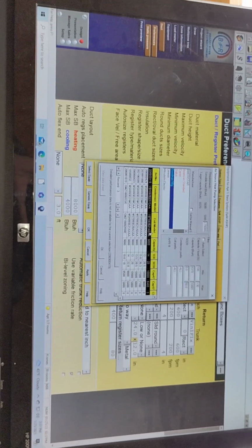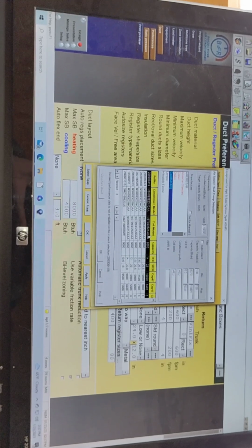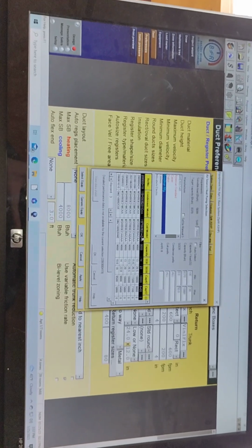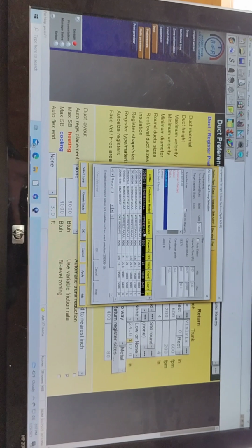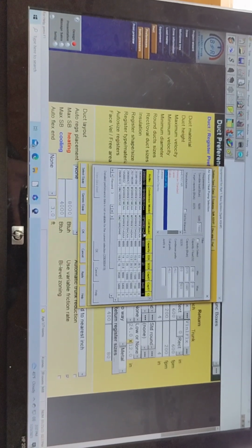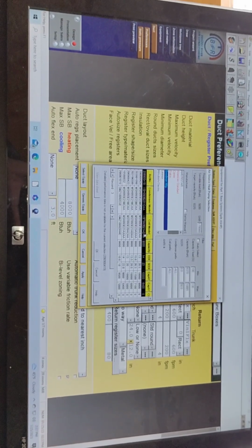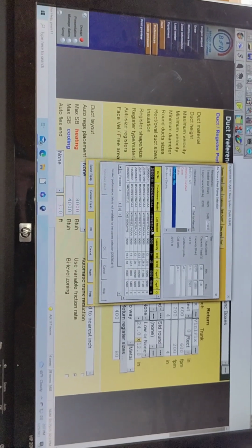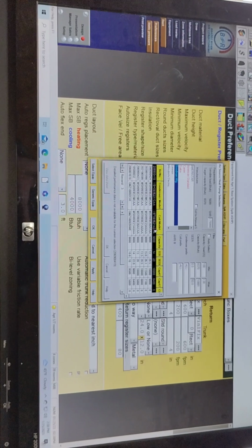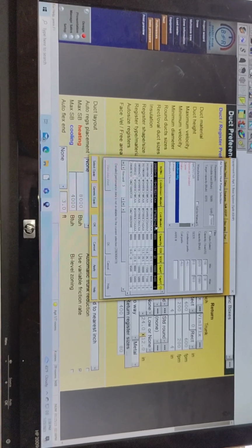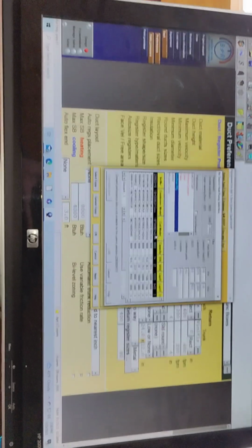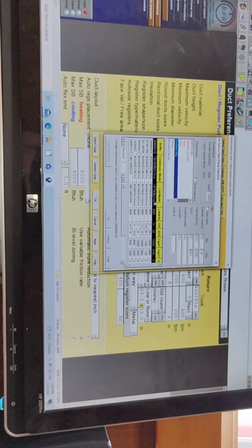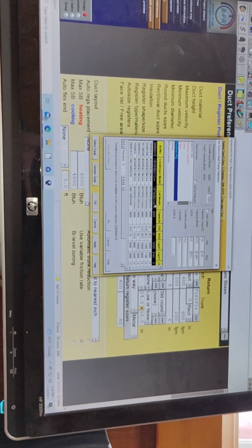They care if it's 80 degrees outside and you're leaving 60% humidity inside and building mold. That's why the Manual S calculation has become energy code. Again, the energy code is not enforced everywhere, but at some point it probably will be. And whether or not it's enforced, it's a good idea to use it in your buildings and homes.